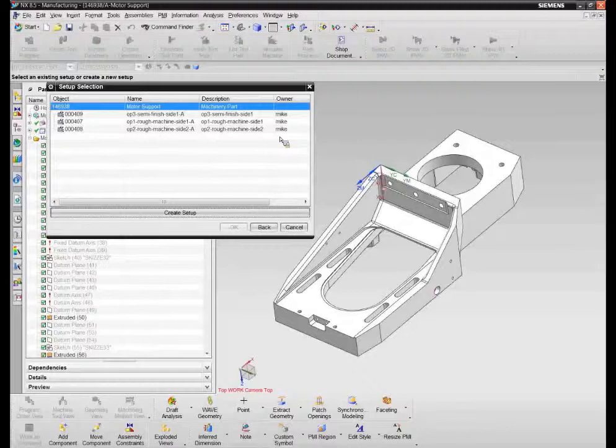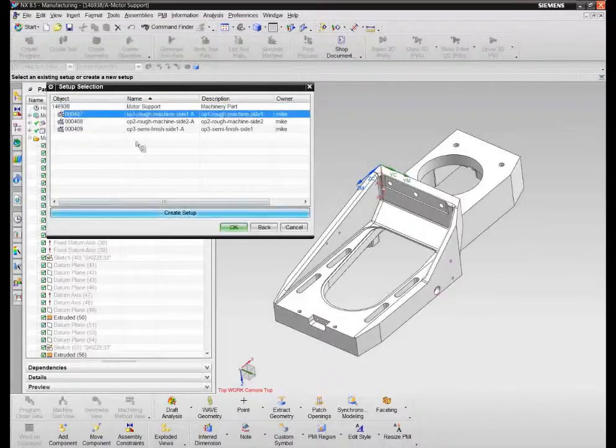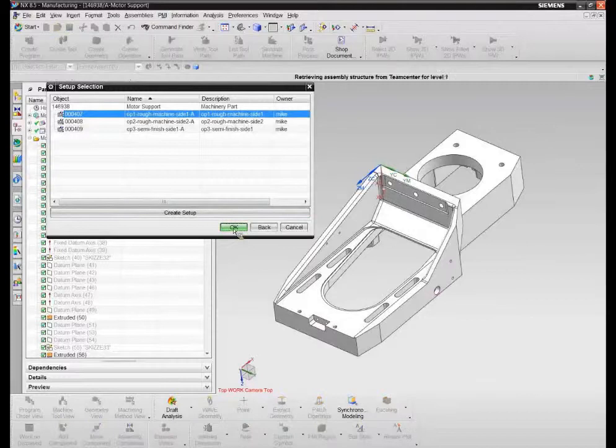So you remember in that PowerPoint slide we saw that we got the part that we wanted to make, the what, and then we talked about the how, the where, and the with what. Well, we've already created 3 work packages, 3 different CAM machining setups, and the system knows that these 3 work packages are related. So I could, for example, open one of these.